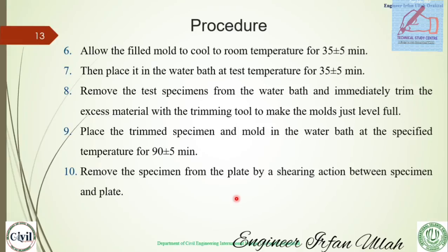Number 6, allow the filled mold to cool to room temperature for 35 ±5 minutes. So you will allow it to cool because you have heated it. You can allow it for 35 minutes according to ASTM, so it will be cooled to room temperature. Then place it in the water bath at the test temperature for 35 ±5 minutes.